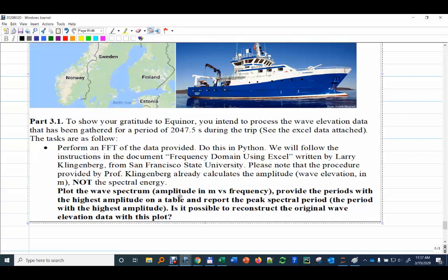And also FFT is a nice tool to learn because you can use it for many other transient phenomena. Like I told you before, if you have some excitation, which can be a force, a variation of pressure, or a variation of rate, and it seems very random, you can apply an FFT and see the spectra.